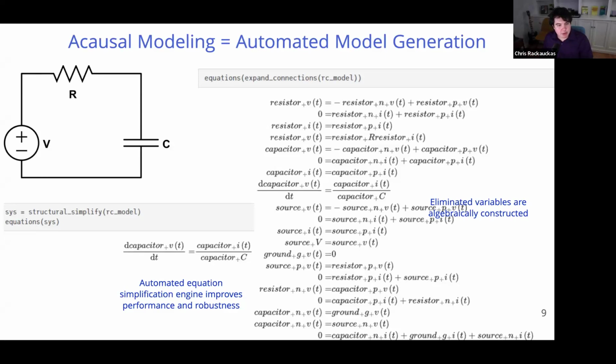Besides cloud compute capabilities, what else does JuliaHub offer? Meaning, are there loop rerolling optimizations at the compiler level in the base open source version of Julia? No. The open source version of the modeling system is ModelingToolkit. It's fully capable of describing and building all these models, but the loop rerolling optimizations and some other optimizations I didn't go into, like linear system optimizations used for multi-body systems, are proprietary to the JuliaSim compiler. So you can use the open source modeling system, ModelingToolkit, to make any of these models, though for running them in the fastest way, you will need the extensions of the JuliaSim compiler.